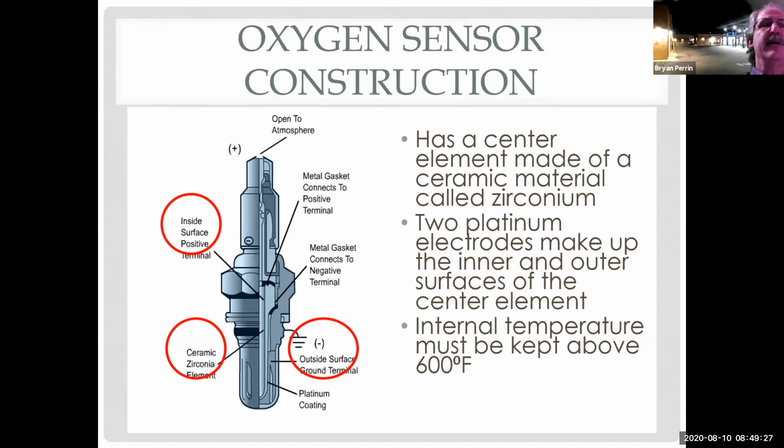So there's only 3 companies that make these sensors. There is Bosch, there is NTK, and there is Denso. So if you're buying a sensor made by someone else, they're either reboxing one of those sensors or they have a sensor manufacturing plant and they're buying them out of China or whatever. Odds are 50% your car won't work right after you put it on. You always want to use the factory sensor.